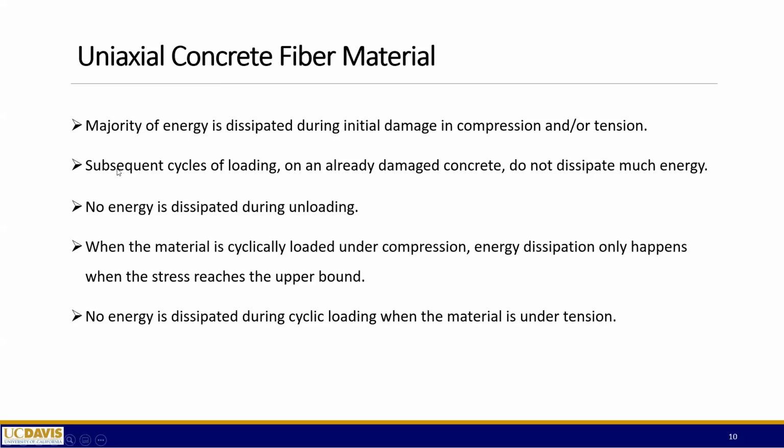Can I say something? Yes. So essentially, when you start bending and you plastify concrete, or you crack on the other side, or you plastify the steel, and then if you cycle back and forth, most of the damage happens in that first loading cycle. Then everything else is essentially just going to step up. Now, if there's more moment applied, then you're going to have an additional first cycle for this additional loading, so additional damage is going to happen. But as long as you cycle within some bounds of moments, the first cycle is going to dissipate most, and the rest dissipates far less.